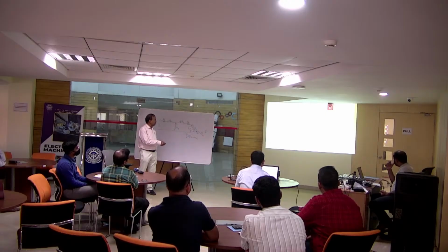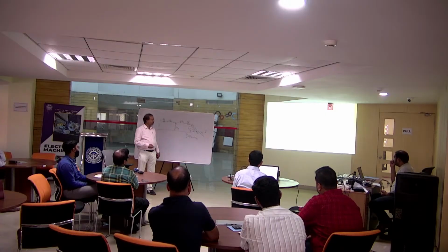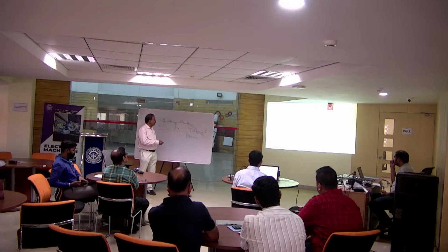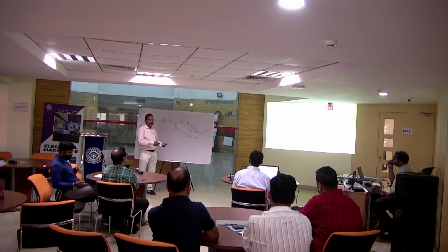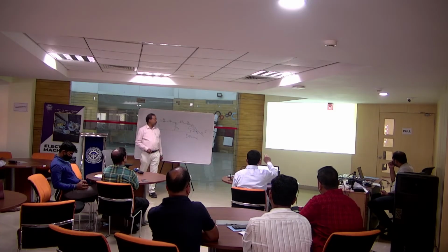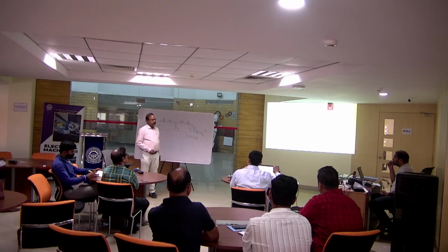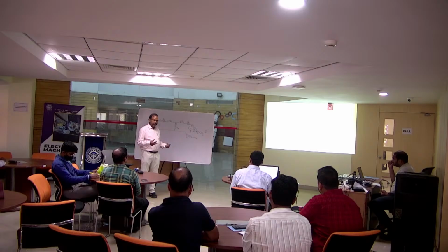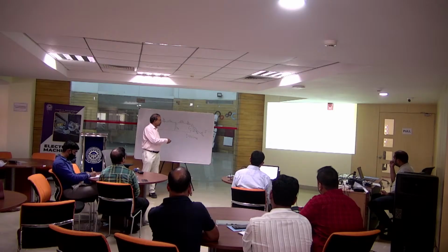This is fed to a DC motor. The DC motor field supply is a separate supply from a separate source, and the DC motor and the induction motor are on the same shaft. So the resultant torque will be additive if the DC motor torque is in the same direction, and if it is opposite, there will be a difference. The DC motor is getting supply from the rectifier on the rotor. Both will run at the same speed, but that speed will be higher or lower depending on whether the torque is additive or subtractive.